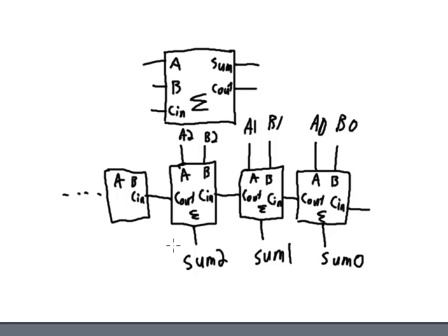And that's why this type of adder is called the ripple carry adder. Now there are other ways of designing an adder circuit to create a faster summer, so that it sums the bits, and each one of the bits, sum 0, sum 1, sum 2, sum 3, etc., are all valid at the same time, with only a 10, 15, 20 nanosecond delay for all of them to be valid. But we're not going to get into that kind of adder in this video.